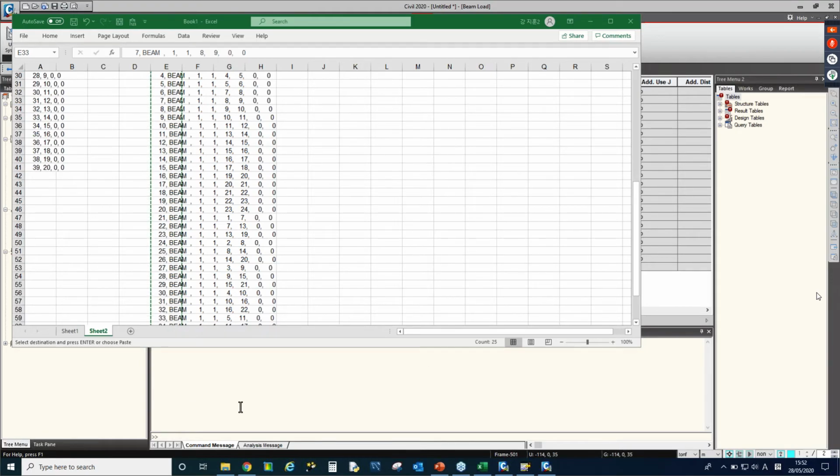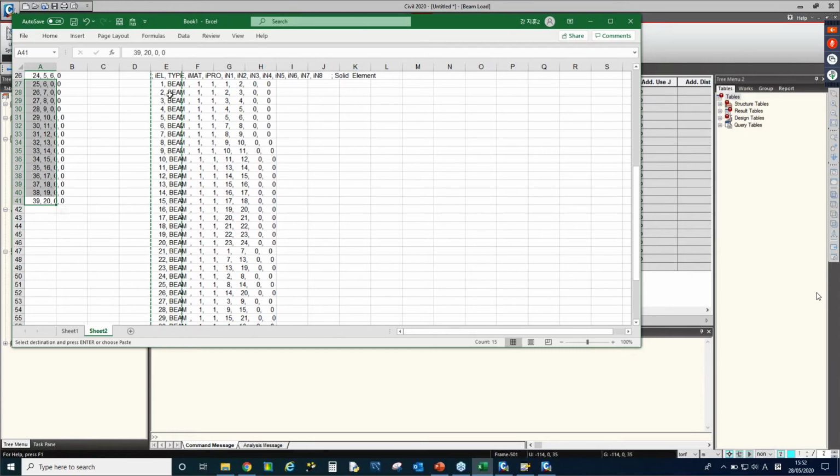Can I define a crossbeam like box girder section by using an Excel sheet and the coordinates? To generate the element, firstly, we need to have the node first. And then when we generate the element, we need to include the node information to be connected to each other. So if you are sure about the node coordinates and the node numbers, you can also generate the element as well, whatever the location is.